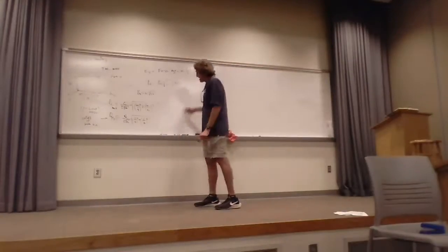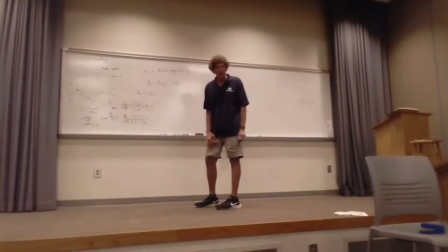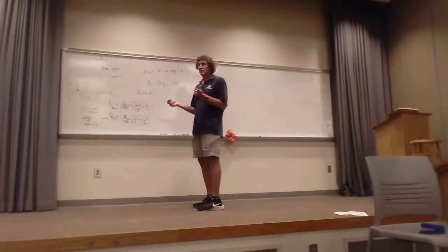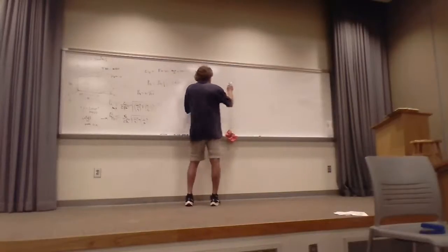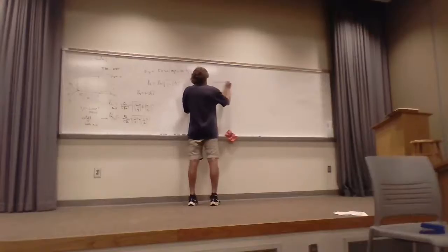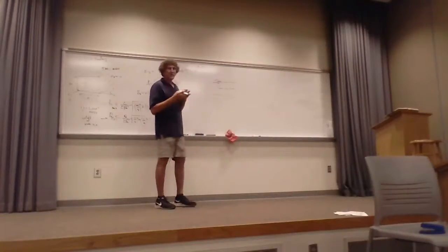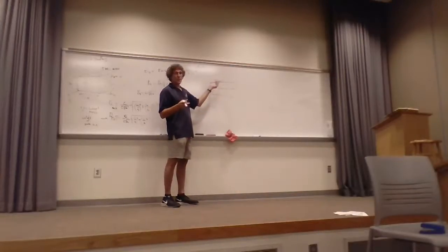All right, so this right here is basically where we were, I think, for the TM modes on Friday, right? Here's some more stuff that's important for TM. And I should tell you, if you're wondering how they actually get this electromagnetic field energy into a waveguide, here's basically how it happens. If I look at a guide just on the cross section, with energy propagating this way, what they do is poke a little hole in there and put in an antenna. It's not deep, only maybe a tenth to a quarter of the way in. And that antenna excites the cavity in the mode you want.